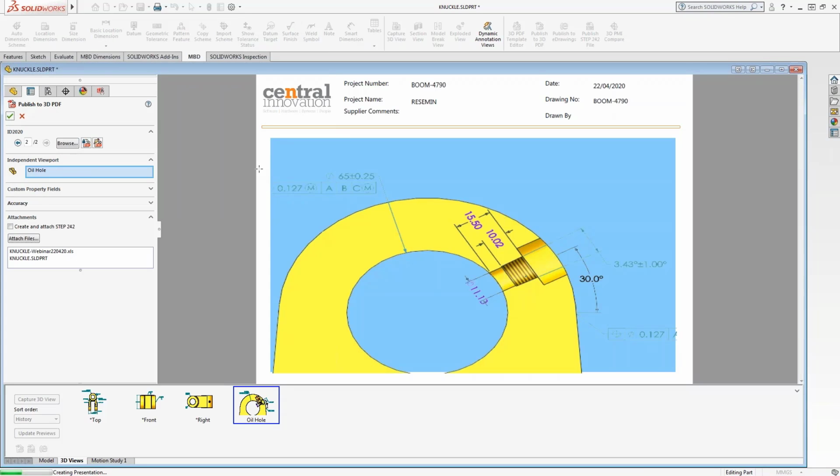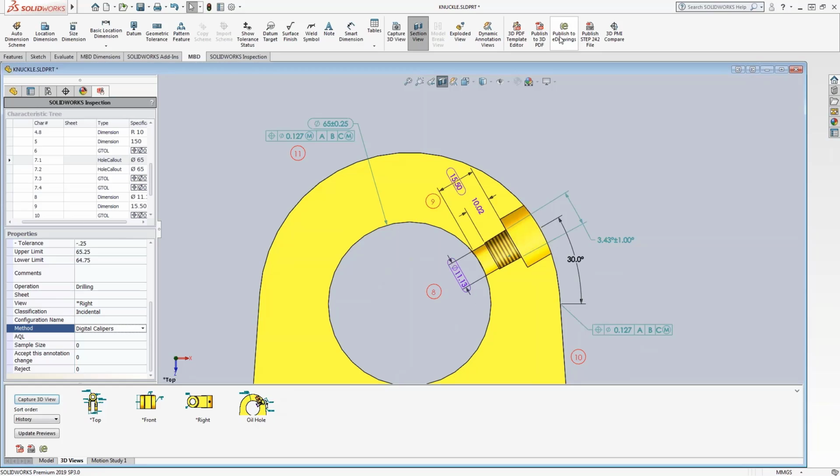That's it. All you need to do is hit save. You've also got options here to publish to eDrawing. So if you want an eDrawing file, you can do that as well. Again, there are other options if you want to add details about BOMs, about any other tables, design tables. Even if you've got sheet metal components and you want to have all the information about the bend tables and bend lines, all of that can be populated within MBD to have a 3D view of it. Yep, so what I'm going to do is I'm just going to open up our saved out file.